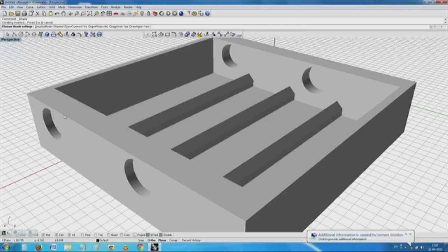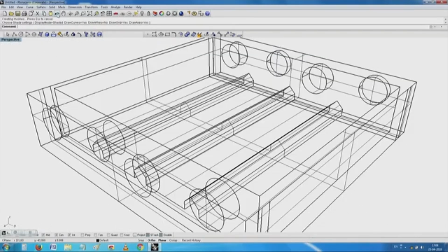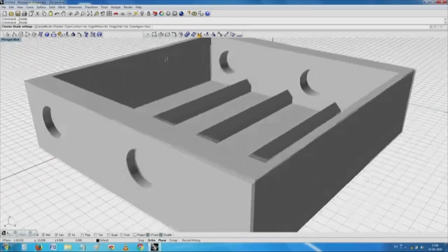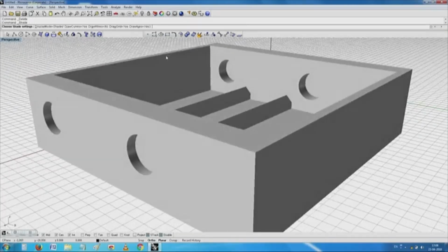So, we will usually compensate by making the opening around 0.3 mm smaller, and after that use a plug with emery, the zero emery which is used for painting, and try to smoothen it inside after the operation is over. So, we used to observe this carefully, and it is easy for us. Now I will go back again and remove this top portion completely. Now you see the full thing has been built, easy enough, is it not?